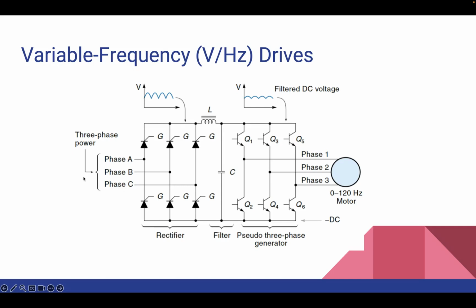Conversely, delaying the trigger pulse reduces the SCR's conduction time, and it can lead to lower DC voltage if the triggering is delayed. And the inductor and the capacitor components that you see in the circuit are used to help smooth out the power pulses from the SCRs, and that is why they are used.